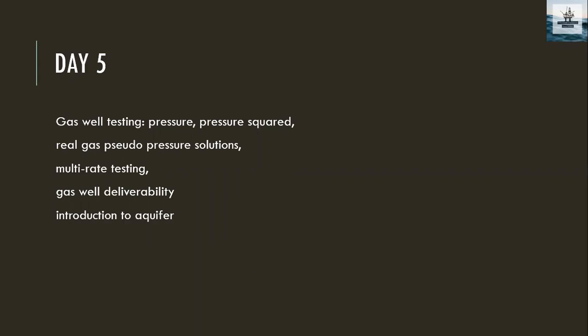Then comes day 5, which starts with gas well testing. In gas well testing we are going to discuss pressure, pressure squared, real gas pseudo pressure solutions, and multi-rate testing. These relate to what we discussed earlier about oil well testing. Right now we are going to cover gas well testing with the help of the pressure squared method. For gas the theory is different, and for oil the theory is different.